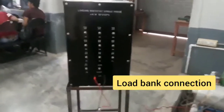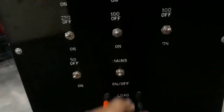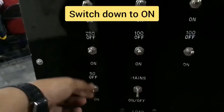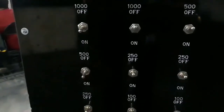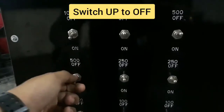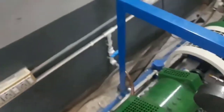Thereafter the load bank is also given here. This is the load bank, in which you can simply see different types of loading is given. So the total capacity here is 4 kilowatt. Then when you apply the different loads in an iterative manner, you can see the different notations written here. So if I turn on the 100 and 500, the total will be 1.5 kilowatt. This way we will give the load to the engine.